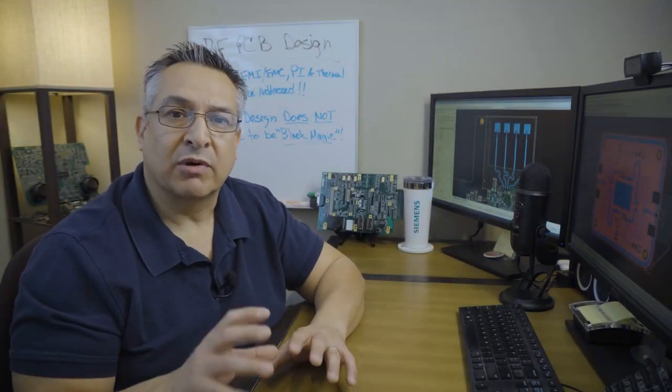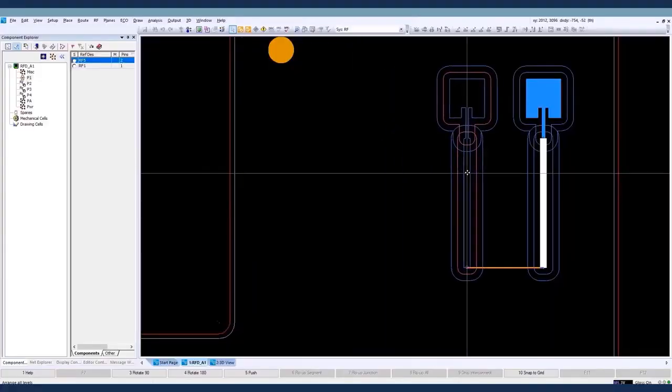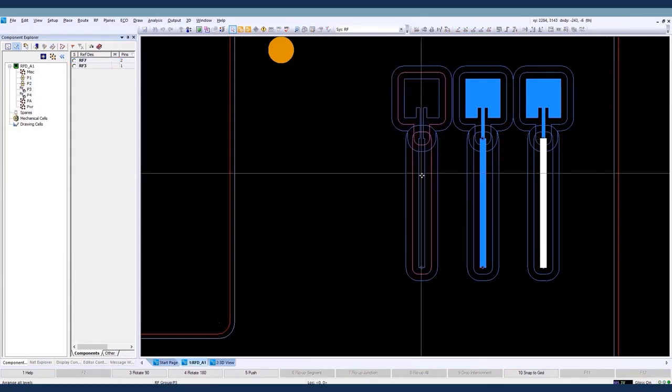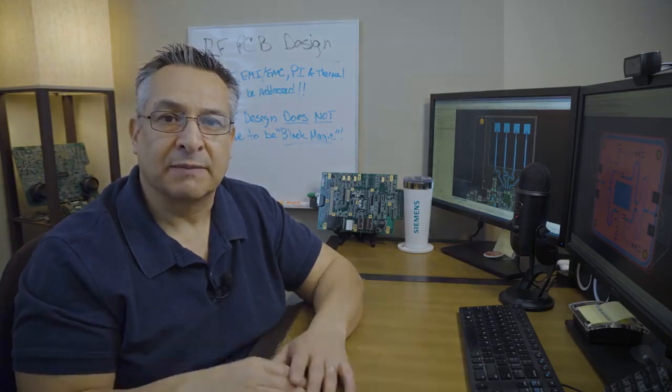Proper grounding is important in RF PCB design to minimize ground loops and interference. Good grounding practices include the use of a solid ground plane and strategically placed ground vias forming waveguides. Decoupling capacitors are employed to filter out the high-frequency noise and to stabilize the power supply.